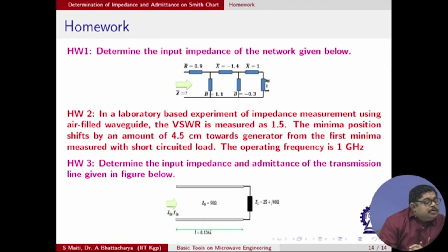So, there is a load and that is in series with something. In the impedance plane you find out those two things, their sums, and then there is a parallel circuit. So, you convert to admittance, find out what the admittance is, then add this admittance, then again convert to impedance, then add that impedance. Like that you can always come to this point and find out what the input impedance is.